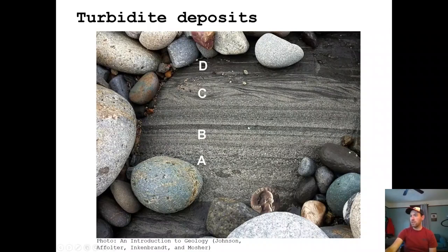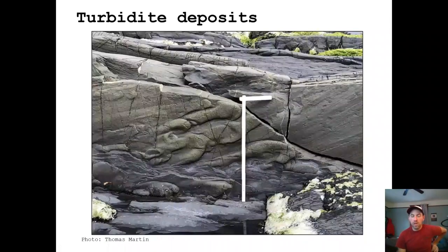A horizon, laminated B horizon, rippled C horizon, laminated D horizon, and then your muddy E horizon would be up here. Okay, and you can see again the muddy horizon down here. So that's the base, and the succession is moving up in this direction. One thing you might expect to see on the base are evidence of loading or traction or scour.